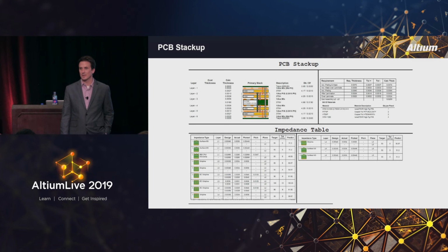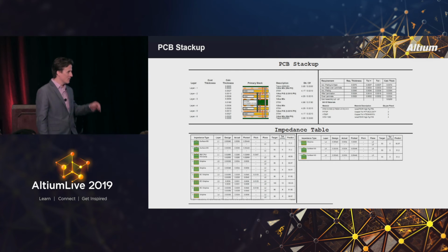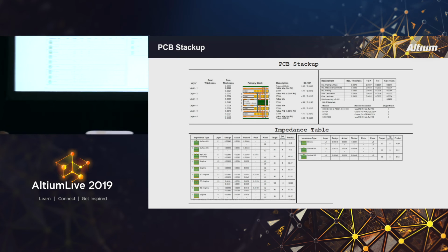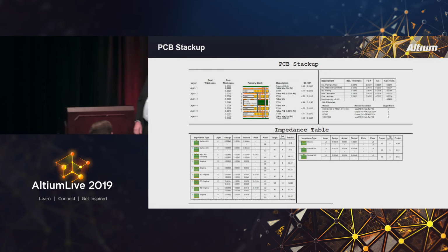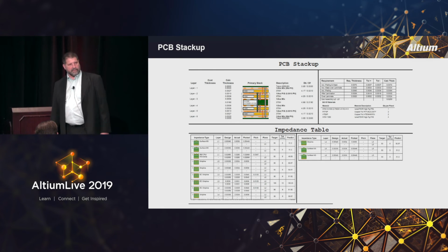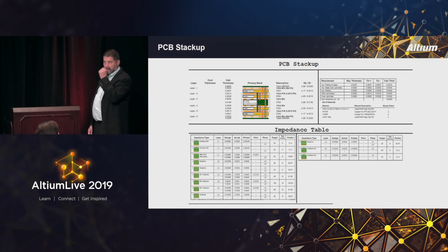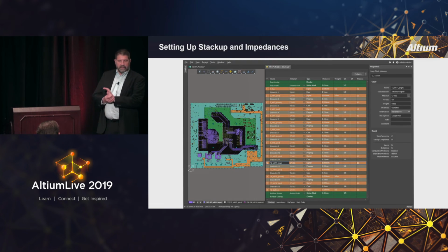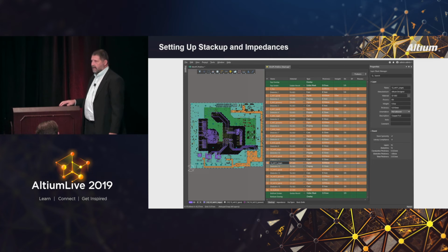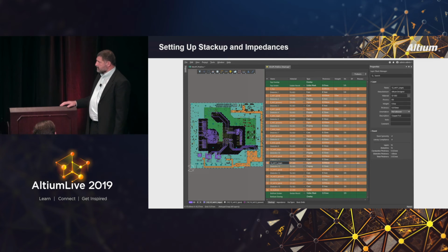I actually had some involvement. Yeah. That is an amazing board to me. Controlling your reference planes is extremely important. I'm super glad to see that come into version 20 of the Altium tools. I think that's going to help all of us be better board designers and to be able to look and find those kinds of errors, because they make a really big difference, especially as the speed of our edge rates increases.